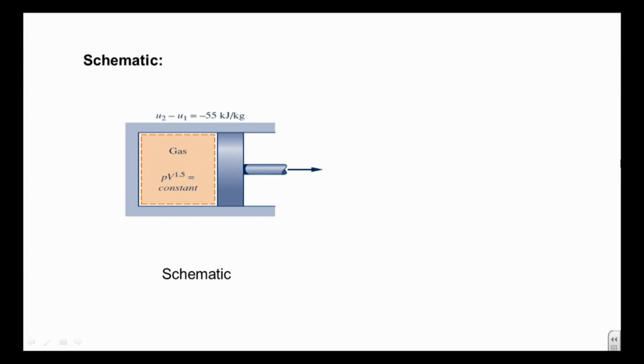The next step in the solution is to develop a relevant schematic. In this case, it was provided to us. However, let's highlight a few key pieces of information to help guide our solution. The first thing to note is there is no mass entering or leaving the piston cylinder. This immediately suggests that a closed system approach is appropriate. Having recognized this important fact, let's select a system boundary. Remember that a closed system does not allow any mass in and out through its boundary.